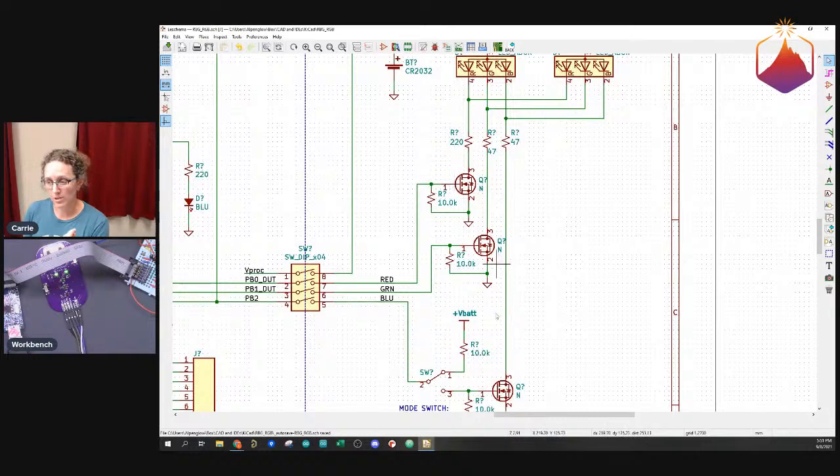And then these are 3 transistors that you can think of as electronic switches, which a microcontroller can tell to be on or off, and they are switching the ground. So when it's off, the LED is not connected and it's not on. And when it's on, it is connected and it's on. And the way that we dim LEDs, do I want to get into this now? I don't know. I'll get into it a tiny bit for you, Brittany.